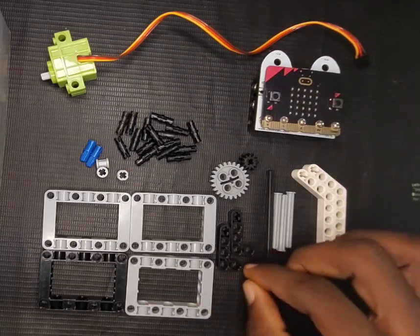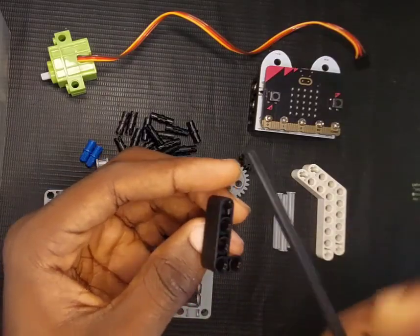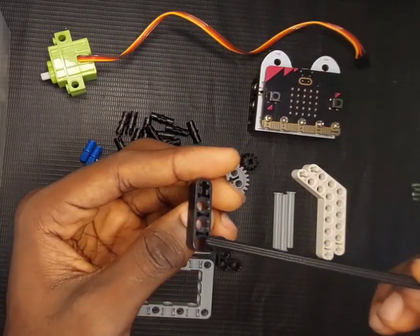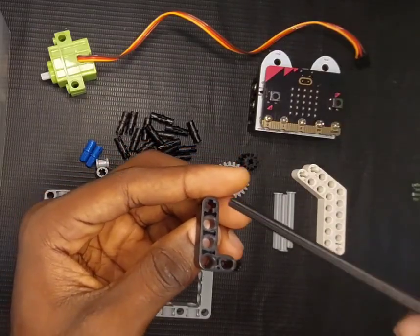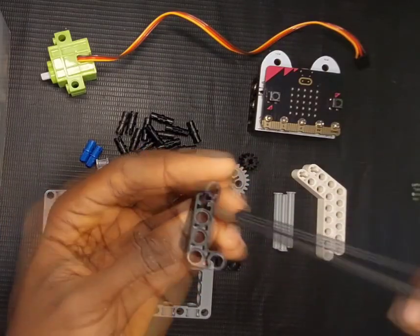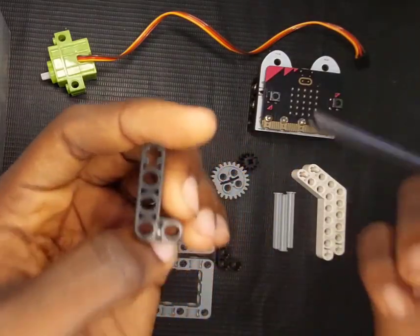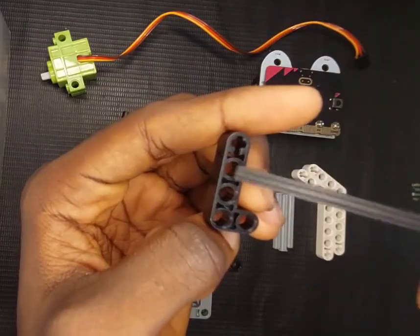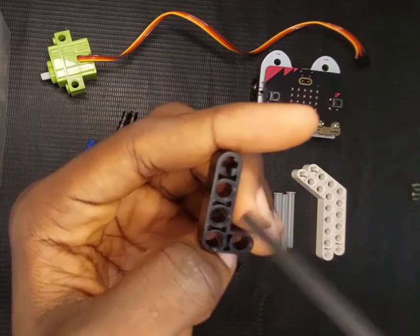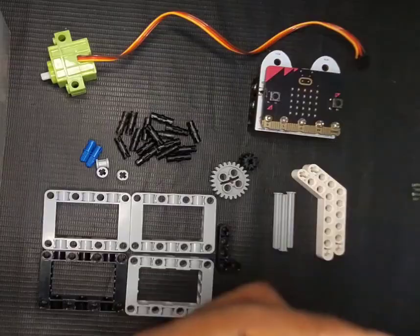Then what we have here are called 4x2 angular beam. And why are they called 4x2? Because on one part we have four holes there, 1, 2, 3, 4. Disregard this axle hole. Generally they are all holes. It's when we become specific we call these pinholes and this axle hole. But for now we are referring to all of them as holes. So it has four holes on this side, 1, 2, 3, 4, and two holes on this side, 1, 2. So 4x2 angular beam. Angular from the sense that it looks like two beams are coming together to form an angle here.